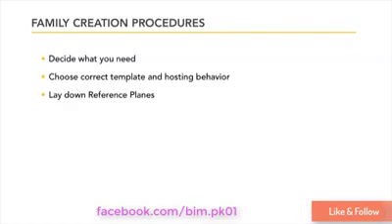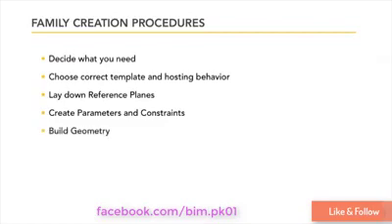We're going to then add parameters and constraints to that formwork, and that's what's going to give us the smarts or the flexibility in our families. So another way we call this is making the family flexible. That's going to mean that it can adjust and change shape and move in size. So we do all this sort of pre-planning and setup before we finally get around to building geometry.